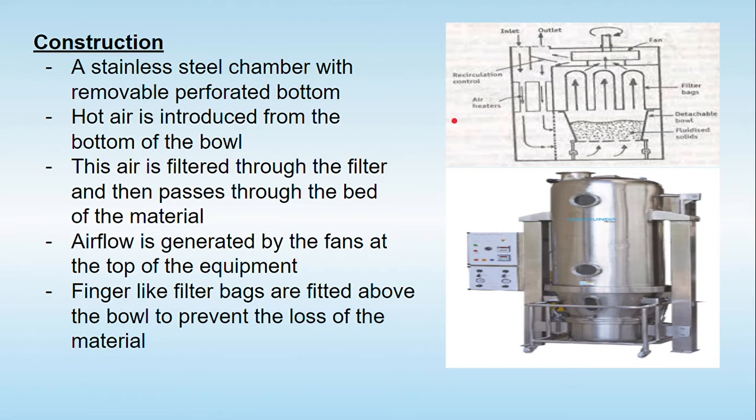I have shown the diagram, and the real picture of the fluidized bed dryer basically consists of this stainless steel bowl, which I'm showing with the pointer, and the bottom is perforated. So this one you are finding over here is a stainless steel bowl, and yes, the bottom is perforated. The hot air is introduced from the bottom. The air from the inlet comes in, passes through various filters, and passes through heaters to get the desired temperature, and it enters from the bottom.